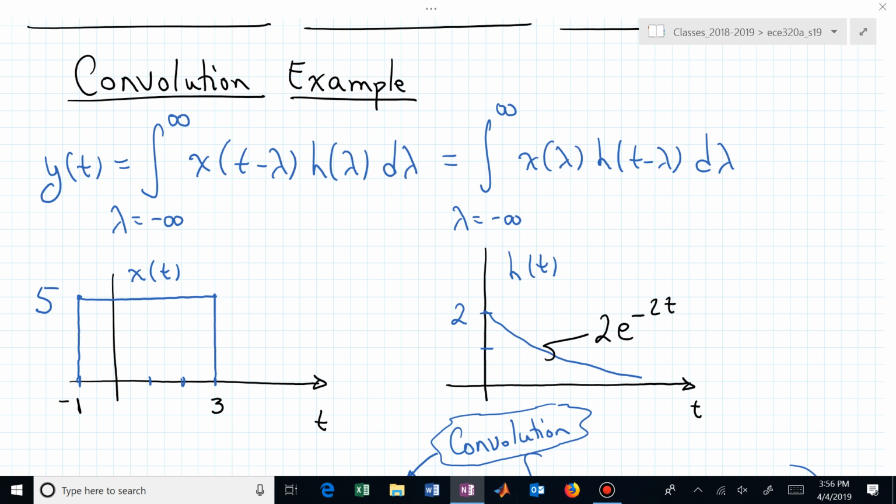But if that filter looked like an ideal impulse, and how would you do that? You would make it much faster. So this would go really high, and then it would be exponentially decaying very fast. So your time constant would be really short, and now the bandwidth of that low-pass filter is quite large. If this impulse response looks more and more like a true impulse waveform, the output's going to look almost identical to the input. But because this doesn't really look that much like a pure impulse waveform, does it?